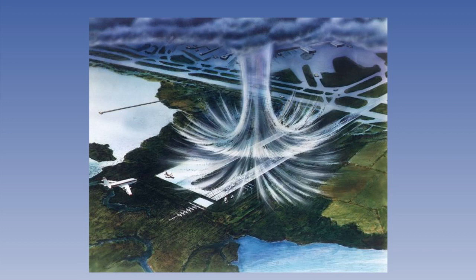A microburst is generally accepted to be about 5 kilometers across and of about 5 minutes duration, although gusts and wind shear can be encountered up to 20 miles from the thunderstorm. The downdrafts generated can be very strong. Over 6,000 feet per minute has been recorded, and can often exceed the rate of climb of many aircraft, particularly in low speed and power situations as on the approach, and the changes of wind direction and speed are large and sudden.